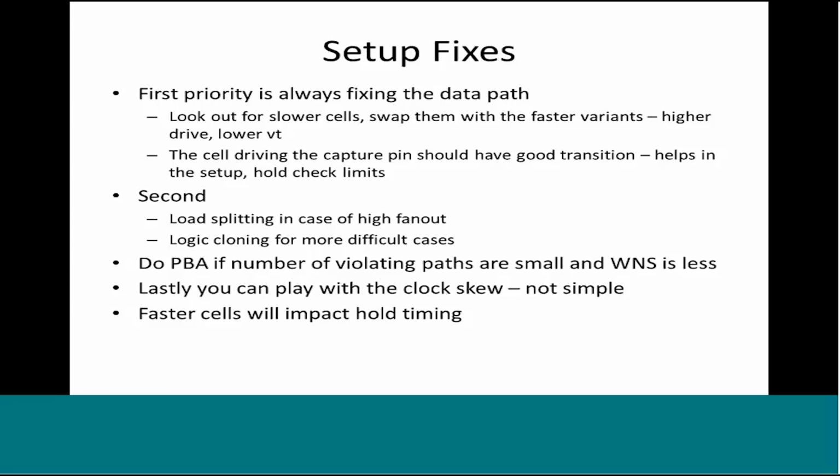The downside is that the faster you make the data path, it might start affecting your hold time, which is expected. Because the path delay has to be between a maximum and a minimum limit, and if you start making things faster, it will negatively affect your hold. It is not necessary that it will affect hold, but depending on the path length, how many start points there are, and so on, it can affect hold negatively.